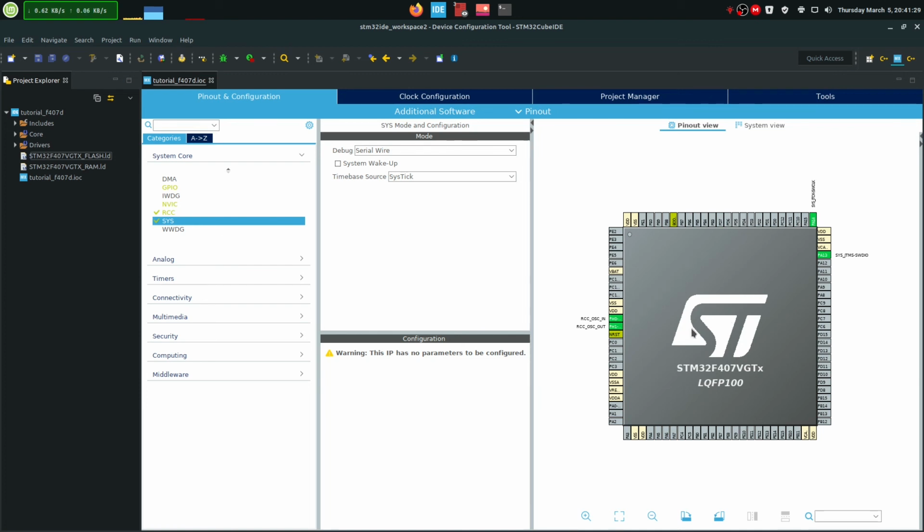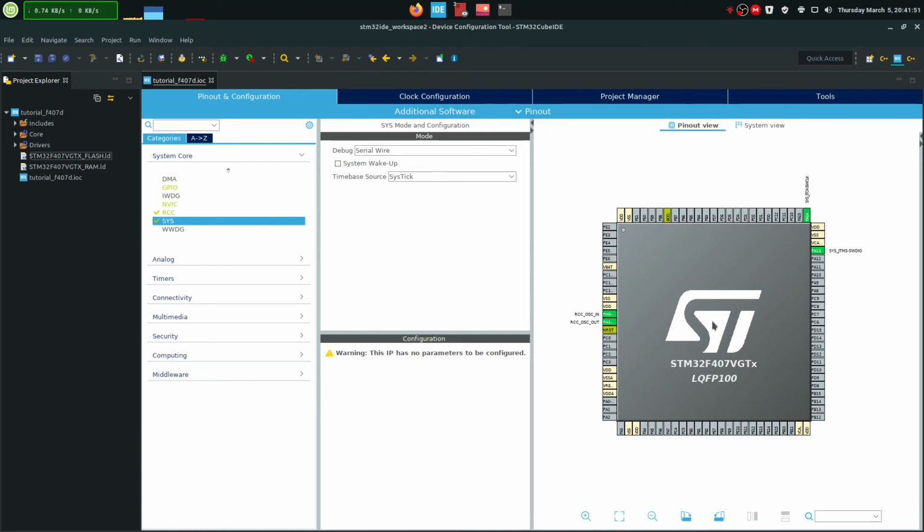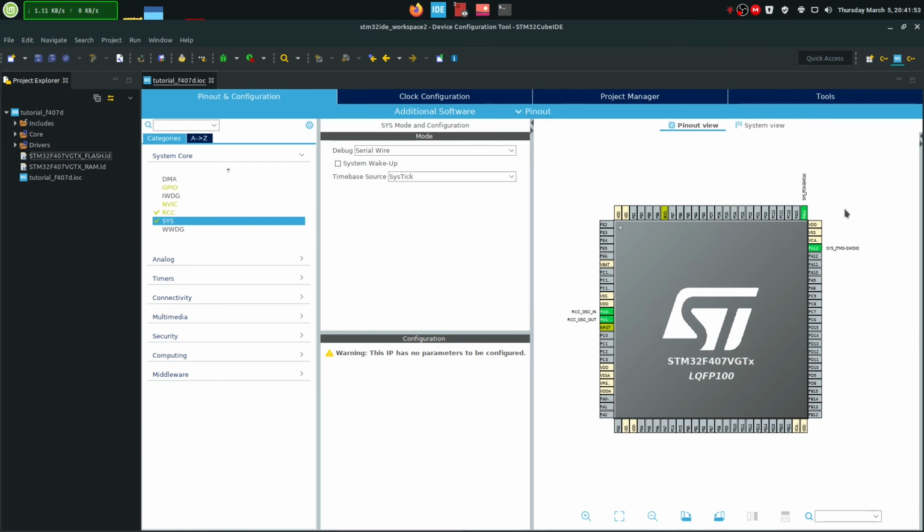I explained in many videos before how to create a blank project, and here I'm blank because, well, you might have a blank MCU or a blank board. So let's not create it in the default state, because I included it as a 407 debug board. It asked me if I want to initialize the peripherals, and I clicked no, and I reset all the pins. The only thing I did is set the clock input and the debug lines, and that's it.